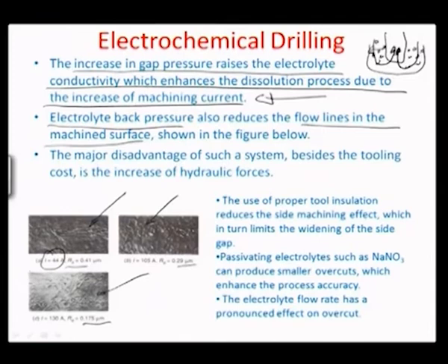If the current is 44 amps, the roughness is 0.41 microns. If it is 105 amps, the roughness is about 0.29 microns, and at 130 amps, it is about 0.175 microns, and so on.